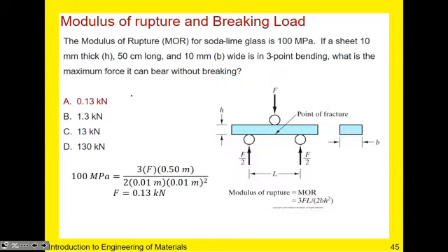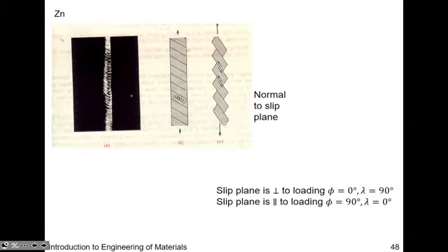Okay. Let me see if I have time for a slip plane discussion. I'll briefly get started, and then this is where we'll pick up next time. But the point of slip and how deformation happens is actually quite important to know for both single crystals as well as polycrystalline material. Because if you're asking, well, how much stress can this material experience before fracture, right? So before that, during plastic deformation, these atoms are moving, and there's a particular mechanism of movement, and it's called slip.